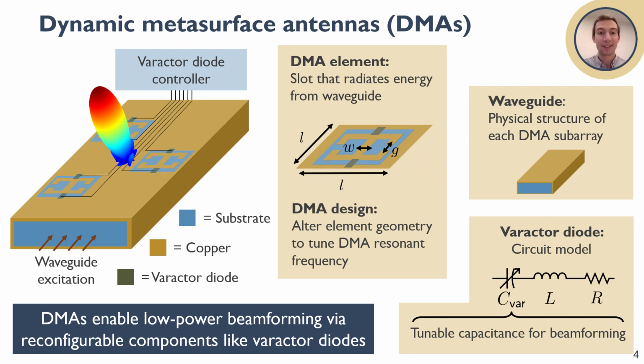And so the slots will radiate out this energy, we can excite our waveguide, and we can do beamforming with low power consumption, since the varactor diodes are passive components and don't really consume any power. And so this really helps us to do wideband beamforming with minimal hardware, minimal cost, and minimal footprint.